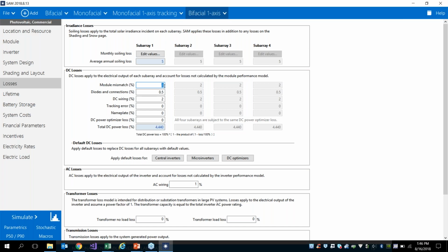So effectively, whether it includes soiling or not on the rear side irradiance calculation. Yeah, those are all great questions. Right now, you cannot specify soiling specifically for the rear side, though I would hazard to say that we still haven't completely figured out soiling on the front side, and so it might be a little while before rear side soiling effects are considered, but absolutely we could see how that would be a valuable place to derate just the component of irradiance coming from the rear side.